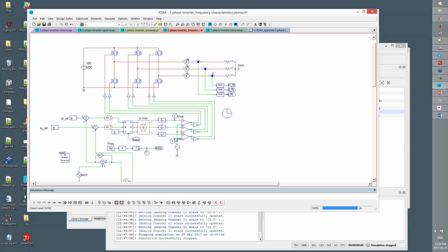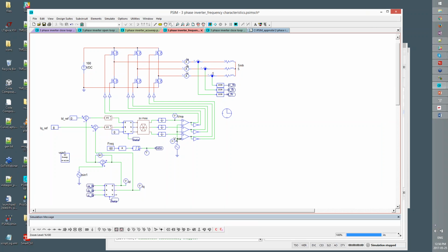Yeah, Ryan, do you have any comments? dSPACE has the MicroLabBox for RCP as their newer version, but they also provide some HIL solutions as well. But obviously, we're going to be a little bit more biased towards our own things. One good thing to note is that the Typhoon simulator with the TI interface card, with PSIM code gen, is all designed for power electronics.